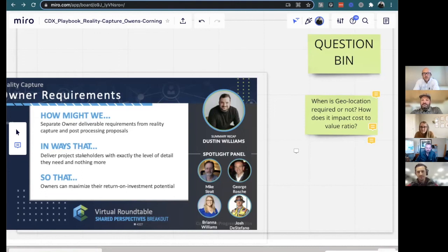I was just on a call this morning where we were talking about our quality framework, and there was an example showing a room completely framed out, and there's a switch in the wrong spot. While it's framed, you can still move that. It takes 5 minutes. But if you've got drywall on both sides and finishes, you're going to take multiple days figuring out where everything is and where it needs to go, cutting holes in drywall and patching and painting. So exactly what you said, Brianna, let's figure out there's a challenge now before we cover everything up.